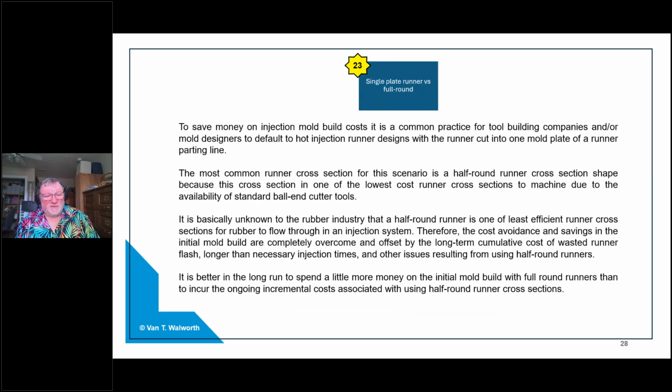When it comes to injection runners, mold designers, mold builders, and process people will say, well, I can use less material if on the runner plate, if I have a hot runner, if I only cut the runner into one plate instead of cutting it into both plates, I save time. I don't have to set up both plates to match and marry and mirror a runner design. I just don't have to. I save money. That way you spend less money on the mold to start with. In my opinion, that